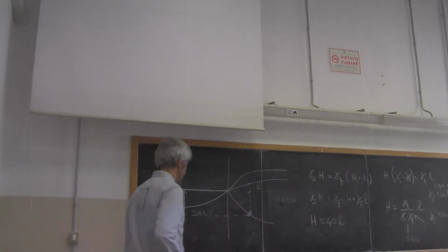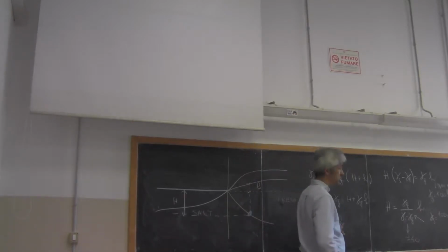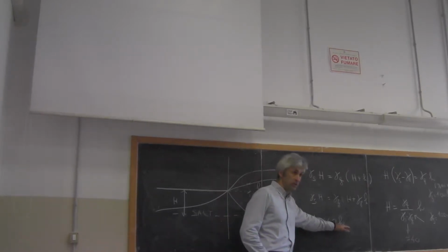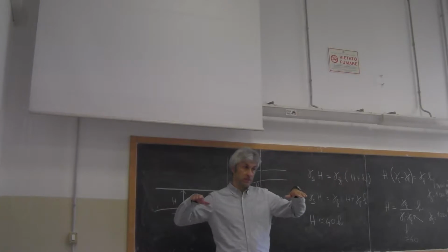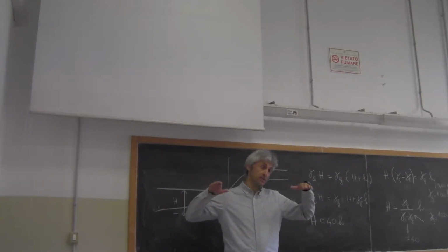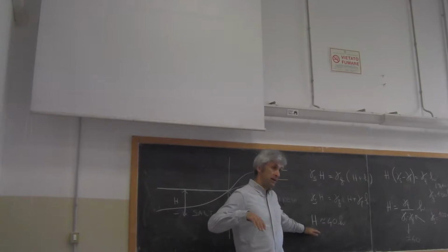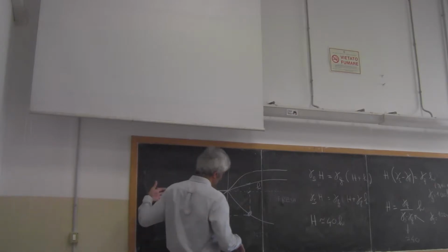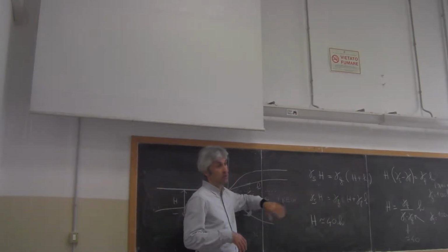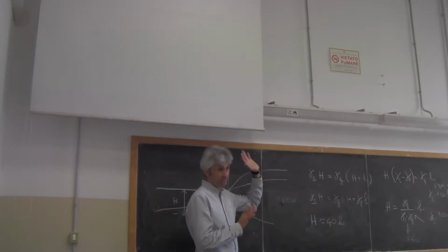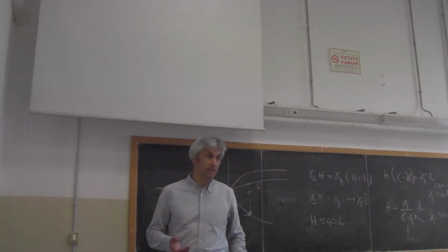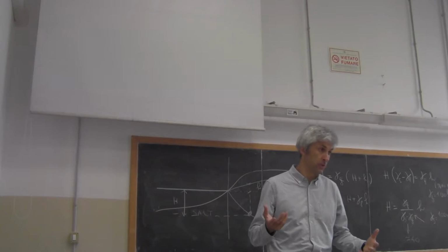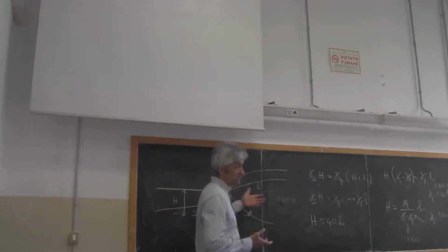And keep in mind that if you take lowercase h 0, according to this model, which means that the water table is at the same level as the sea, capital H is 0, which means that salt water goes inland indefinitely, forever, according to this model, which is something that is intuitive, understandable, because given that salt water is heavier, it goes into the land.